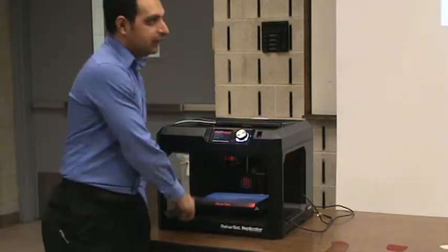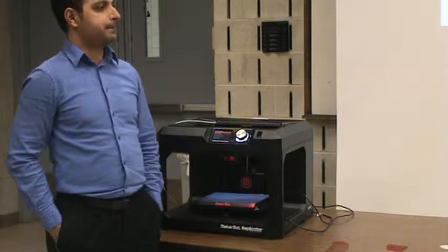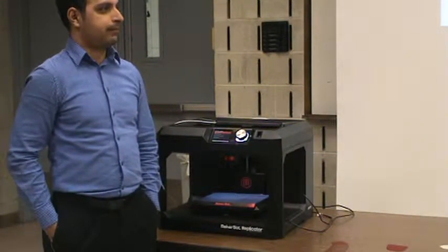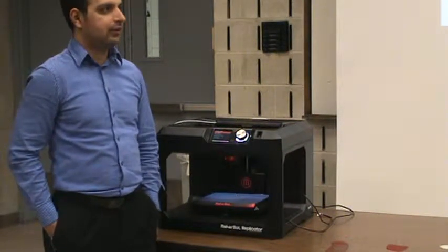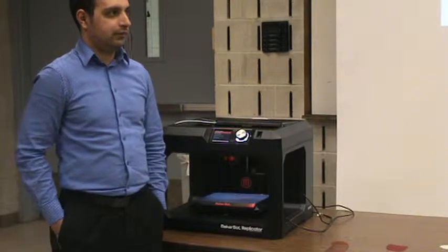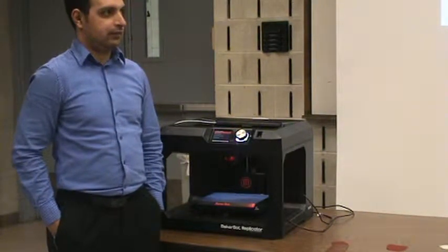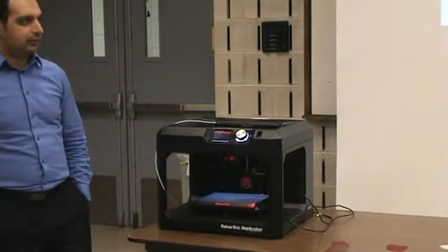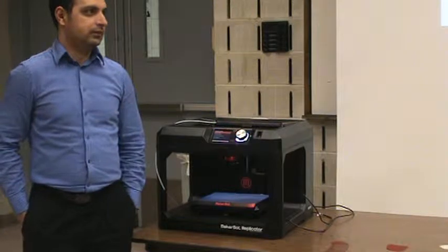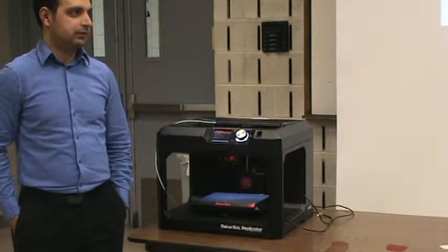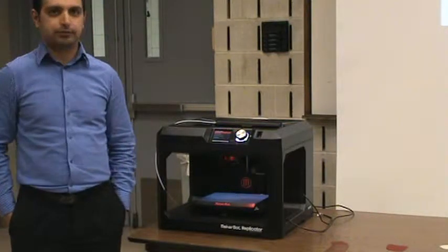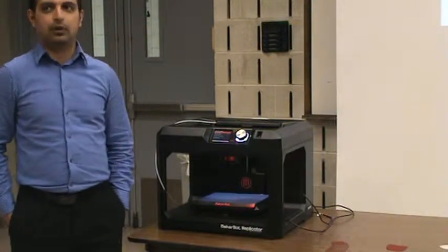I printed three or four times, and based on my experience, sometimes the nozzle stops, so it doesn't print a couple of layers, and then it starts coming out again. At that time, you need to stop, otherwise it cannot handle the missing part. It's pushing down, so it will be messed up. So once you realize the nozzle stopped and a couple of layers are missing, stop and do it again. Any questions?